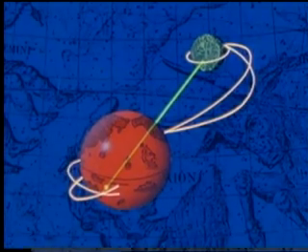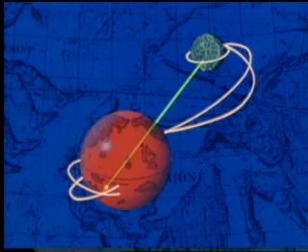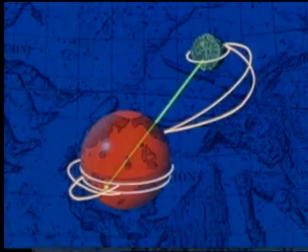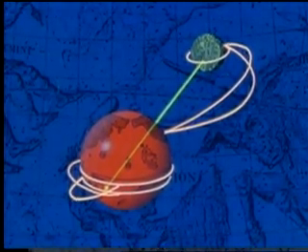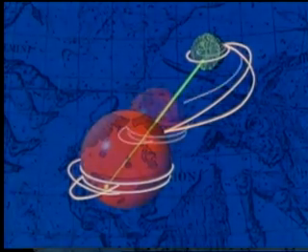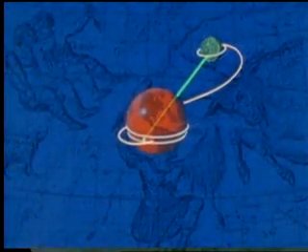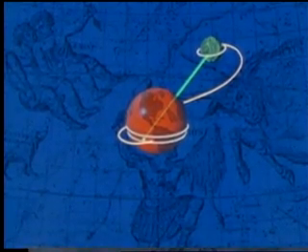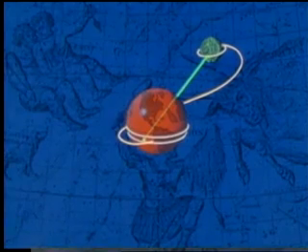This range of planes, along with the entry range limits, determines the range of latitudes that can be achieved. Because of the relatively short entry range and thus the small distance from the antipode to the target point, it can be seen that the latitude range is quite small. The landing latitude selected within this range is essentially fixed at time of trans-Earth injection.